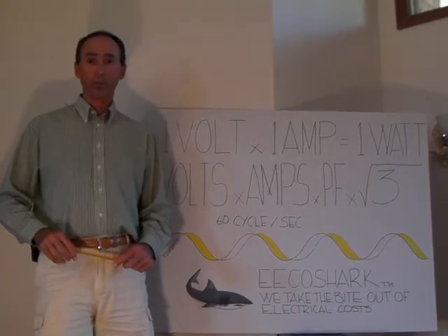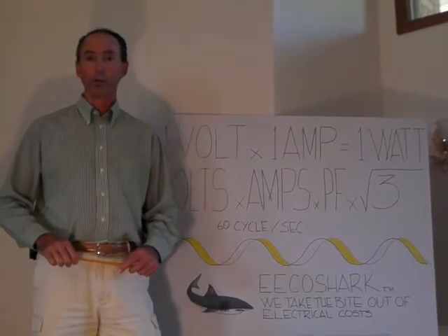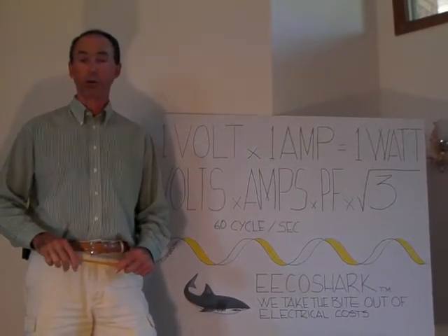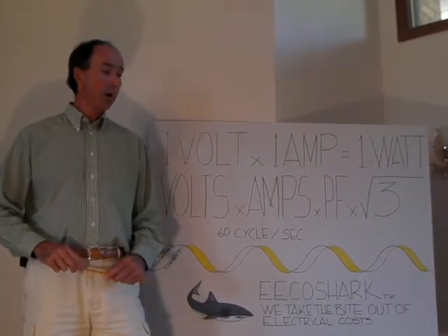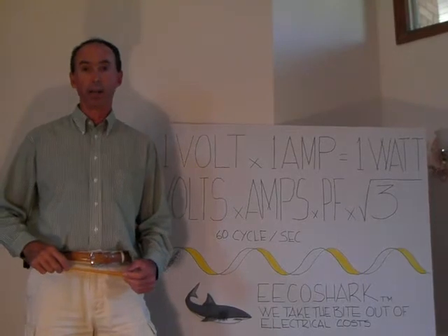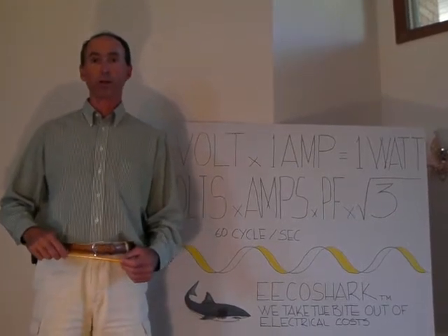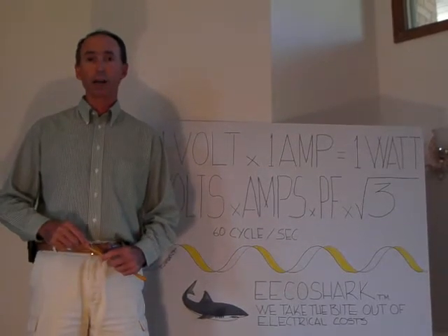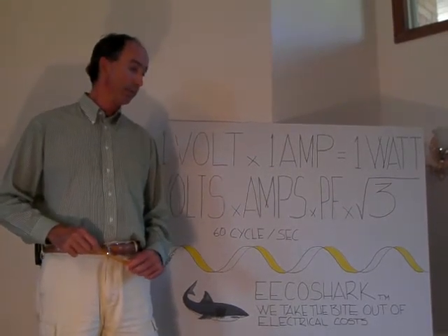On your commercial power bill, you're going to be billed for several different things. The first of which is probably going to be kilowatt hours. You're also going to be billed for a problem known as power factor errors, and that is expressed as kVAR costs. You're probably going to be charged for some component of demand, and that might be peak demand. And peak demand is acquired over the course of the previous 12 months on a 15-minute billing cycle for the highest demand that your facility uses in that 15 minutes.